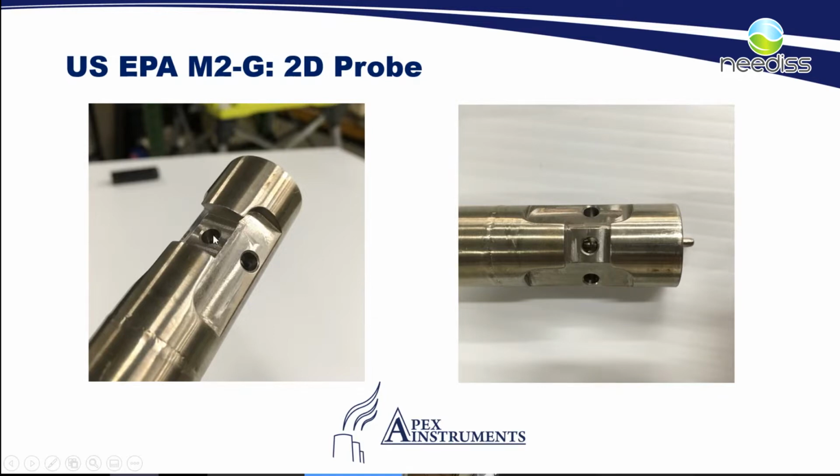And you can see on either side of the probe, at very specific angles as determined by the EPA, we have our yaw angle pitot inlets to help us measure any yaw angle, or what would most likely be cyclonic flow coming from right to left or left to right inside of the stack. So this is an image of the pitot head.